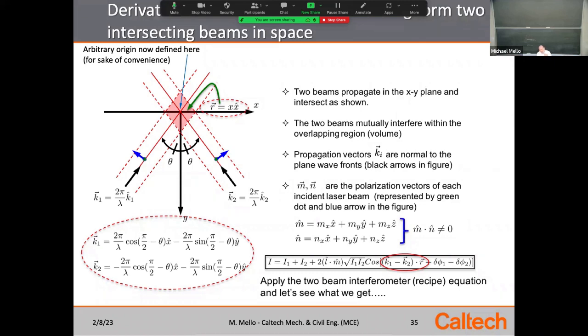And I said, if that was a case, and that's a very common case, by the way, that's the case where people are measuring normal displacements, okay? Whether it's full field or pointwise. And the point I want to make before I close this whole module out is that the recipe to understanding anybody's interferometer, I don't care whose it is, you need to read and think about the path length problem in their configuration.